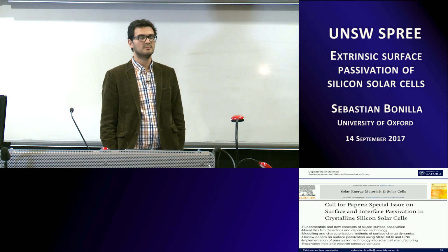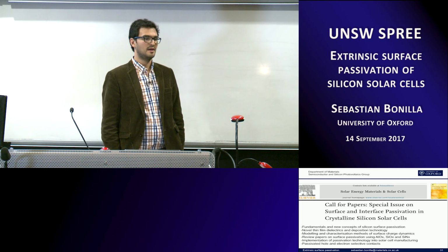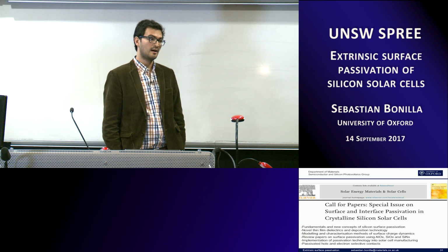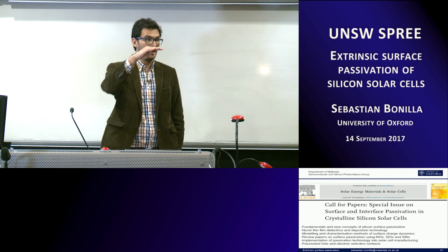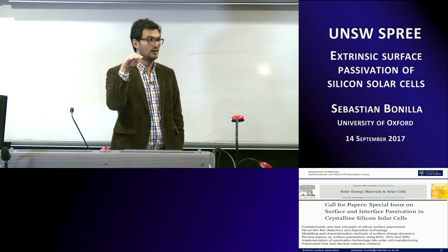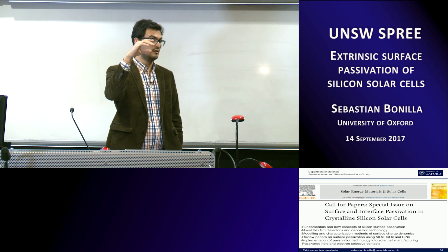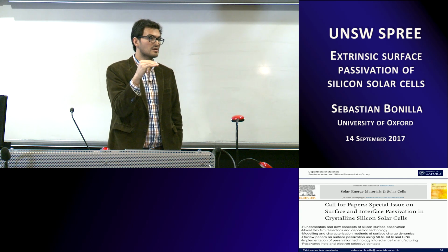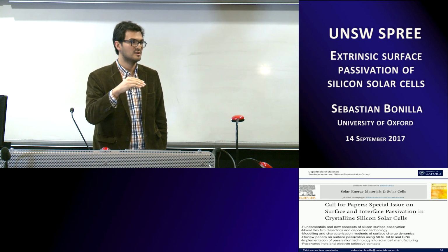Now, I guess the straightforward point about that is the fact that PID is somewhat solved already, and the solution in most cases involves depositing a very thin, highly conductive layer as the outermost layer on a dielectric stack. All that does is prevent a high electric field from falling between the top of your dielectric coating and the interface to silicon, which is where the ions would sit.